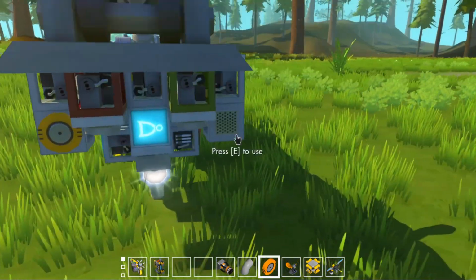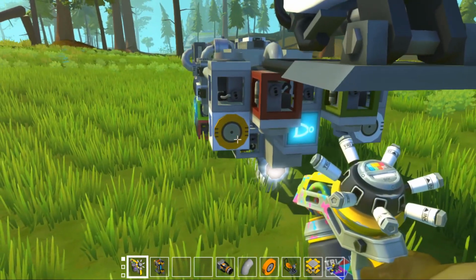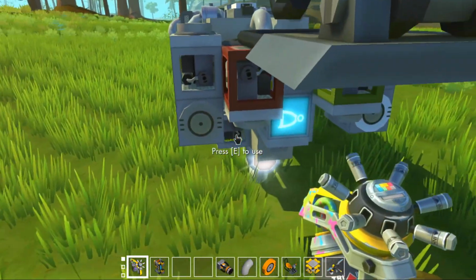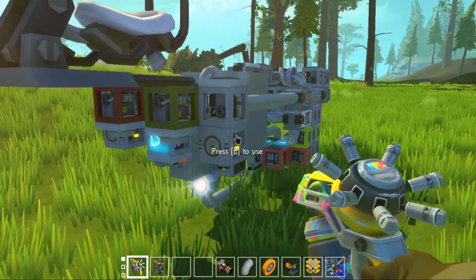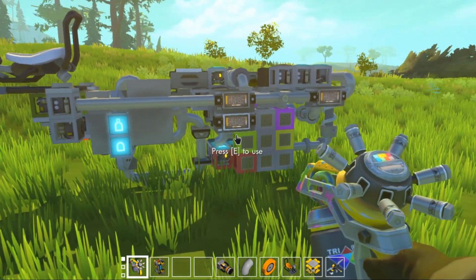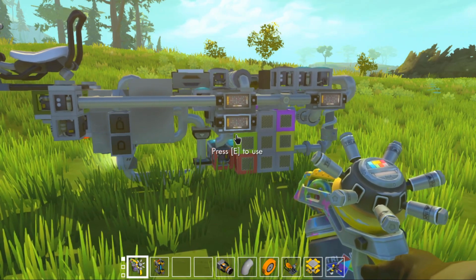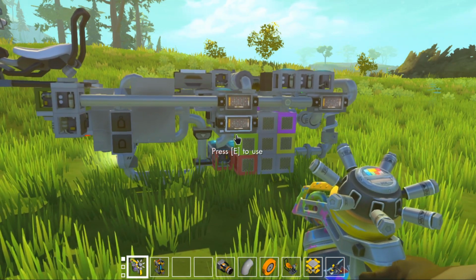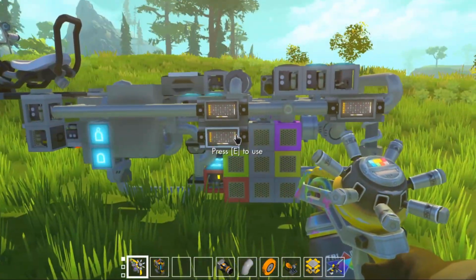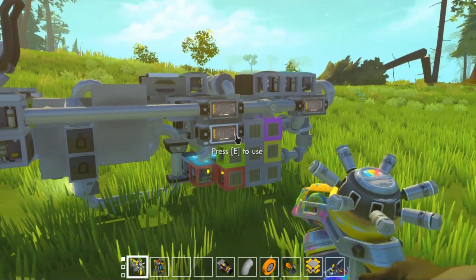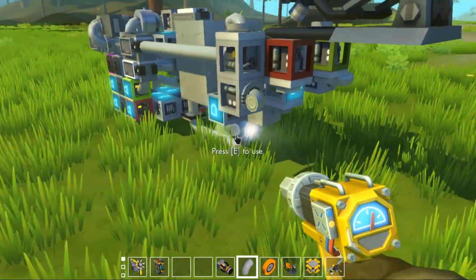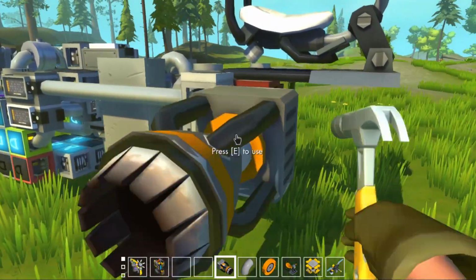Let's get a first set of thrusters. Oop, I accidentally painted the wrong thing. Now you want pairs of thrusters, two thrusters pointed in the opposite direction, for this to work. In my old main flight computers, they had 8 possible thruster clusters. This one only has 3: front, back, and middle. This is set up so if you want to use it as a helicopter, you can. But for now, we're going to set up just 2 clusters, front and back, which also means that the vehicle needs to be symmetrical.